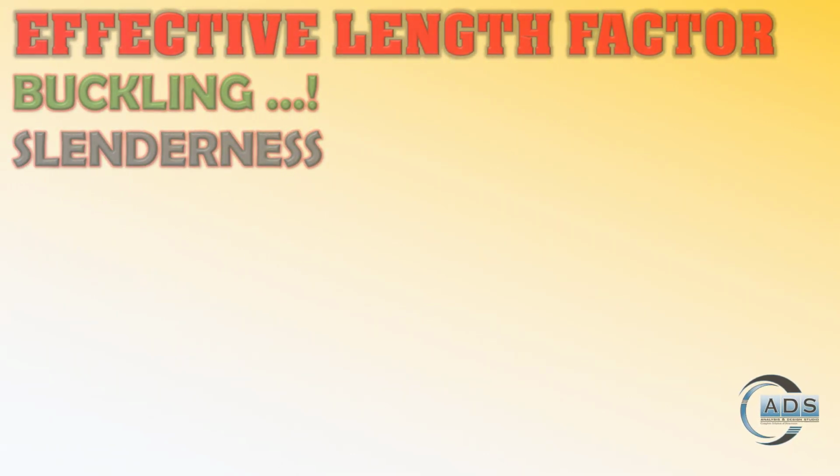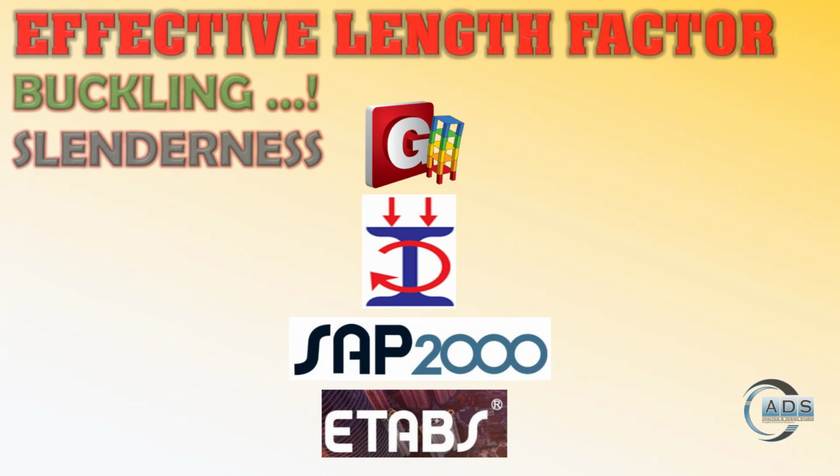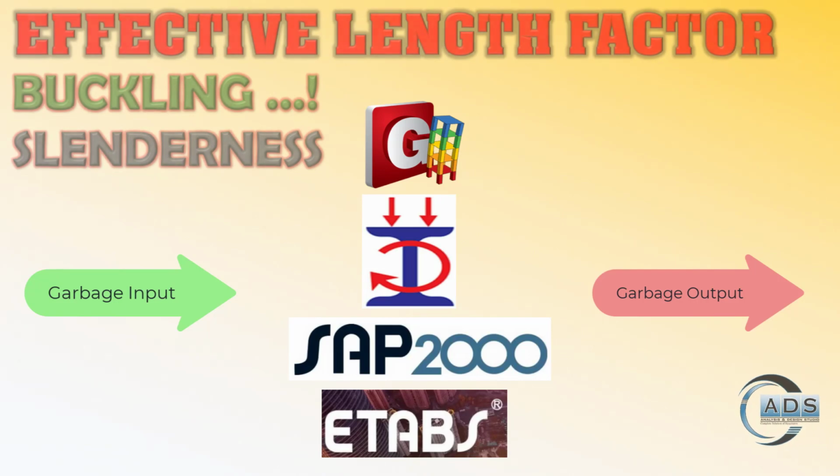The reason for explaining the concept of effective length factor is so that we can be confident about the values calculated by the software. Because in structural design, whatever software is used for the calculations, the main thing to remember is garbage in, garbage out. So it is necessary to keep an eye on the calculations made by the software.